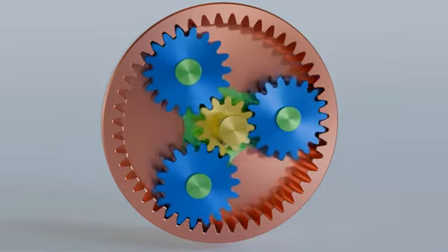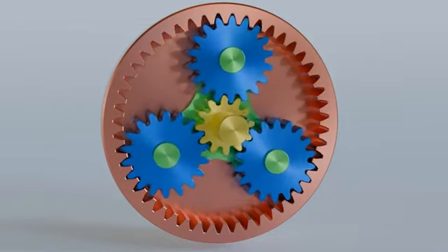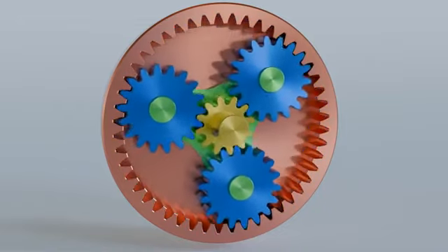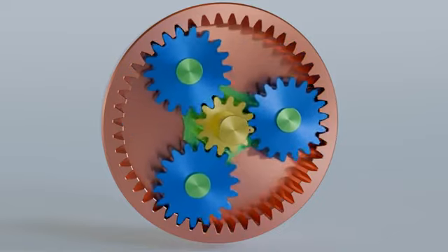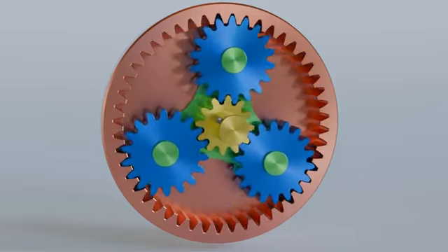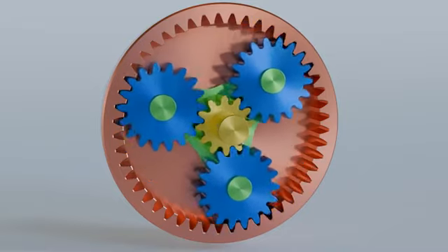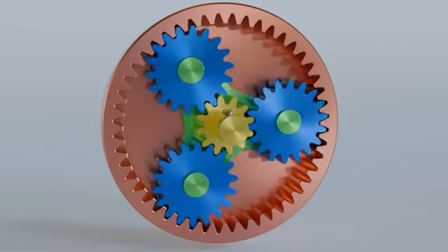The advantage of a planetary gear compared to a conventional stationary gearbox is the compact design and the advantage that all shafts are arranged coaxially. For very large transmission ratios, several planetary gearboxes can also be connected in series.